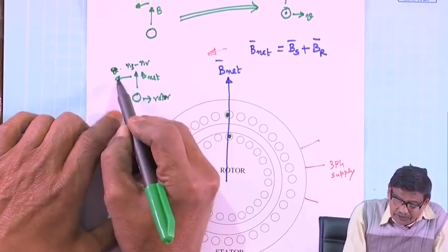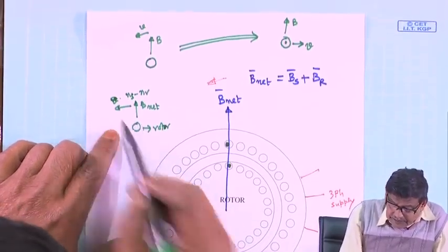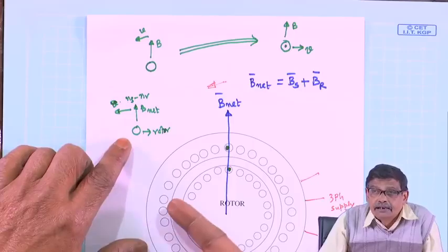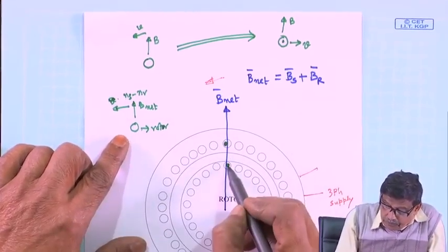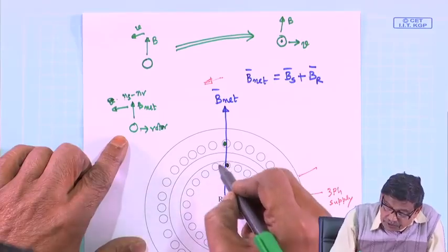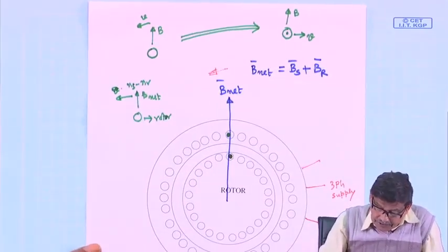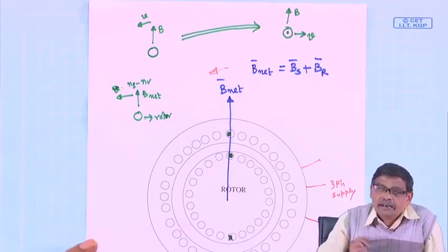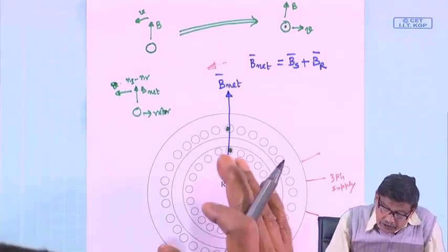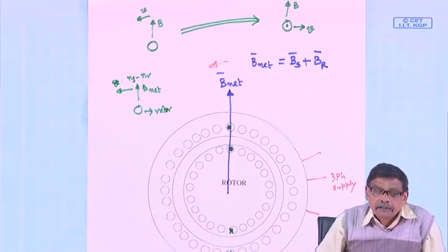So, corresponding to that whatever is the tangential velocity, and then since ns is greater than nr, I told you, the polarity of the induced voltage will also be this is dot, this is dot. And for obvious reason, on the other side, whichever conductor is there, this will be cross cross like this. So, this will be the polarity of the induced voltage in that.